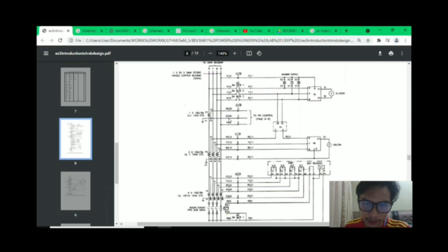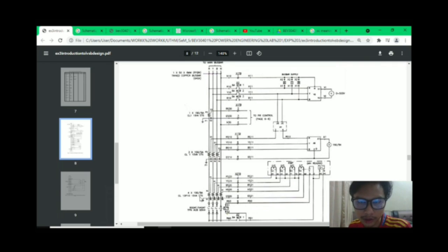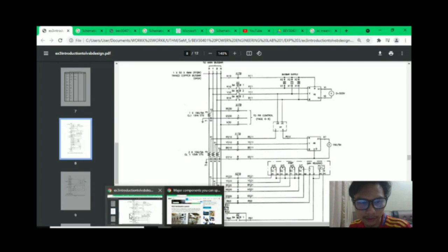They connect to the 10P10 15 VA CTs. 10P10, the P means protection, and the connection is four wires: 3 overcurrent OC and 1 earth fault EF. All of this connects to our protection relay. So back to the simplified one.